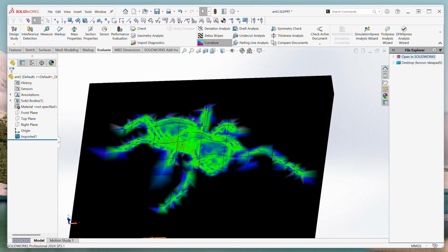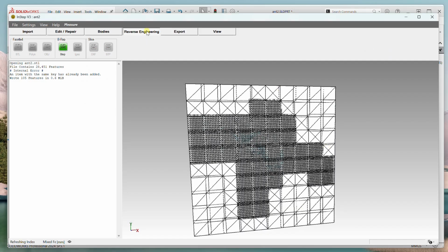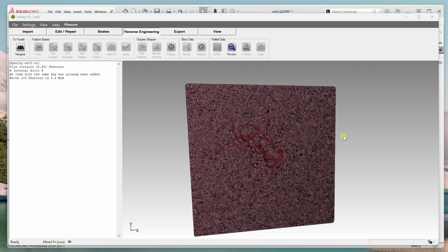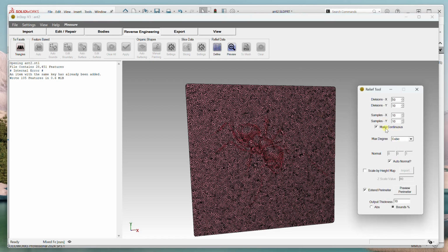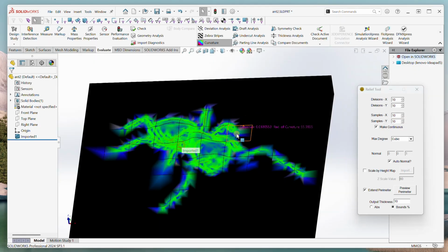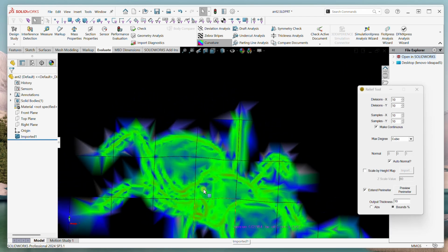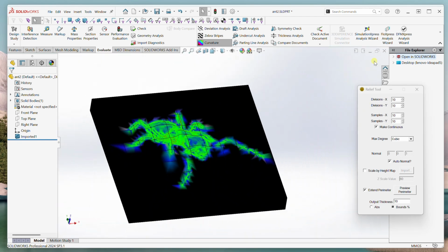and that's got to do with the fact that the definition here, make continuous, that's G1 continuous. If we wanted to see a smooth continuation across the surface, this would have to be a G2 type continuation, which the application currently doesn't support. So keep that in mind when you're looking at some of this stuff. It's G1 continuous. Now I want to show how this is different.